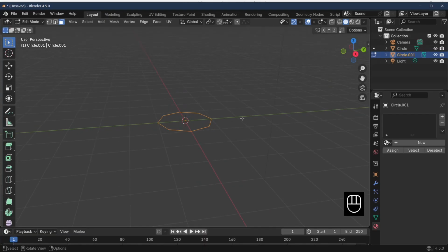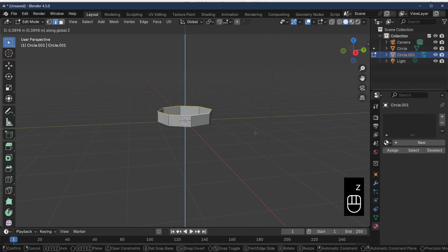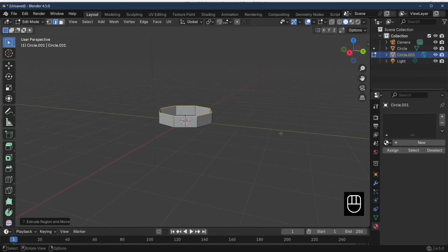What we can do now is select your points, your lines or your faces. But we're going to select the line there. Press the Alt key, we'll select all. There's another way to select all, which is to press the A key. So E to extrude, in the Z, and we've extruded it just like that. Extrude means that it moves the shape in a particular direction that you want, and it duplicates a face to make another face.